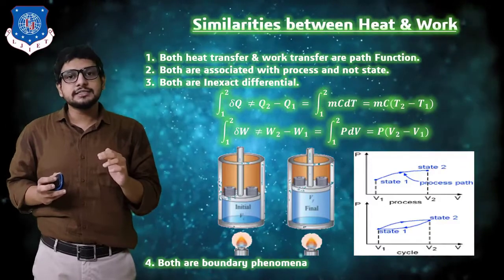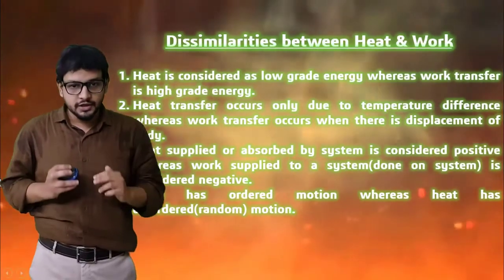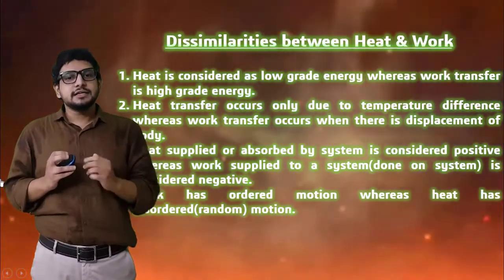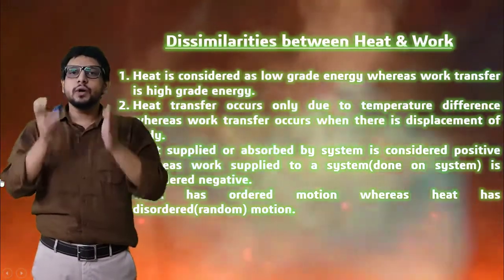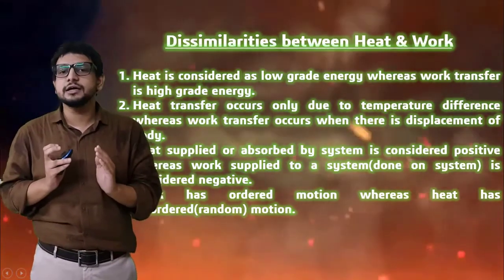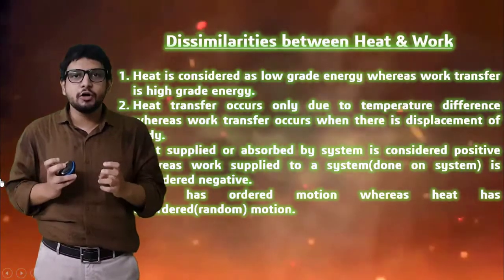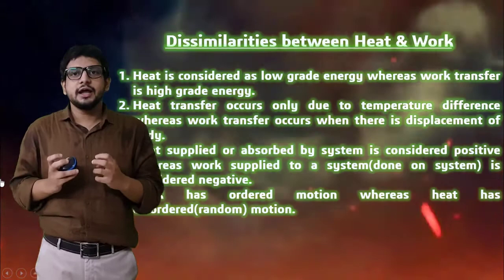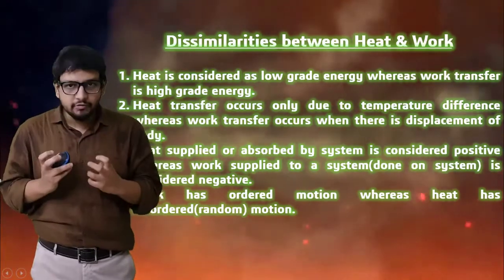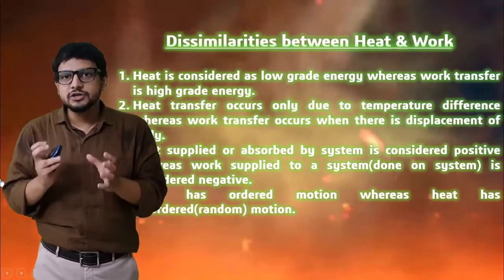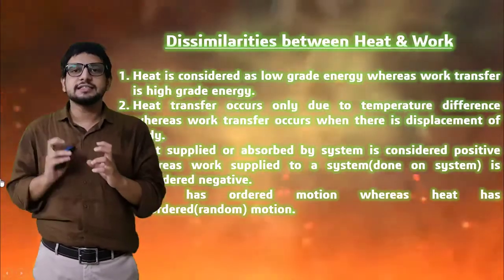Now let's see the dissimilarities between heat transfer and work transfer. The first dissimilarity is that heat energy is considered a low grade energy, whereas work transfer is considered a high grade energy. Taking a simple case of an IC engine, which we have already seen in our last session, in an IC engine, an air and petrol mixture enters the system, it generates mechanical power by combustion, and after that the exhaust gases leave the cylinder through the exhaust valve and a silencer, right?